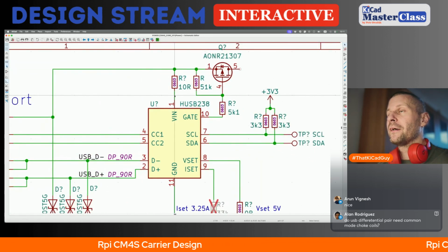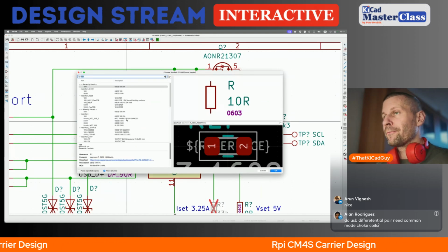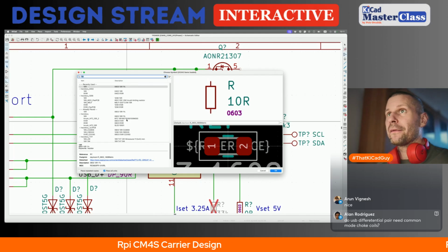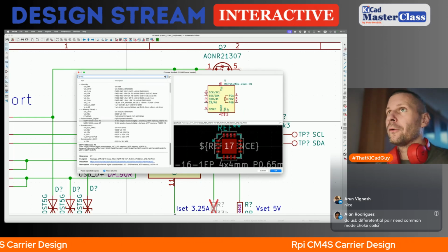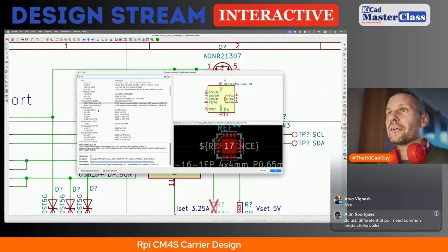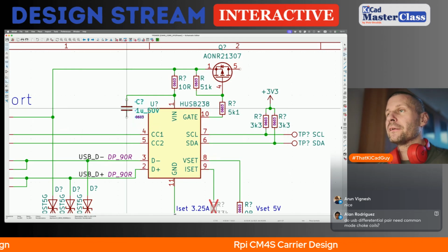For second, it allows you to disconnect the input voltage from the IC if something happens with the board and you need to debug it. So 100% I agree with placing the resistor there. Good design. That's definitely a good design.